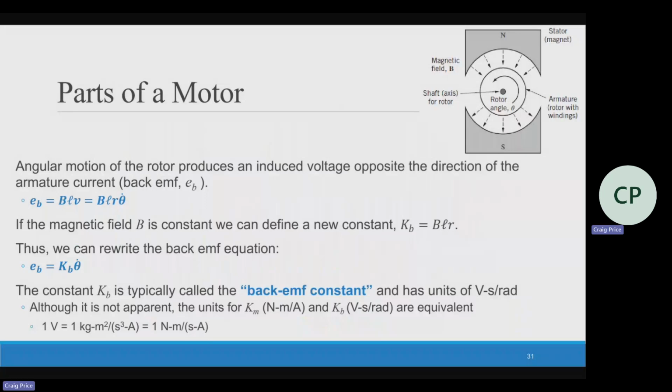You will notice that as the coil rotates, the commutator rings connect with the power source of opposite polarity. As a result, on the left side of the coil, the electricity will always flow away, and on the right side, electricity will always flow toward. This ensures that the torque action is also in the same direction throughout the motion. The coil will continue rotating.